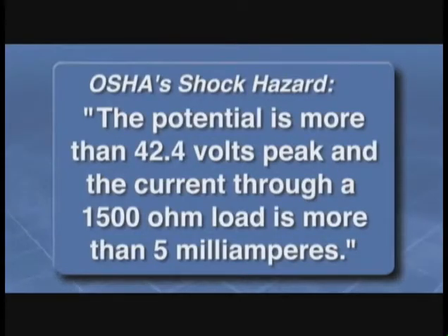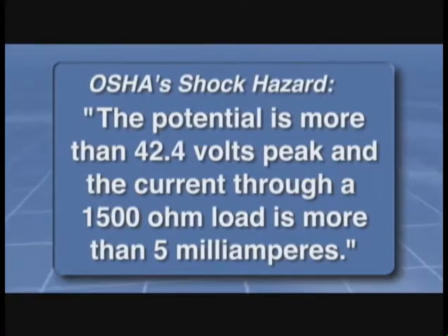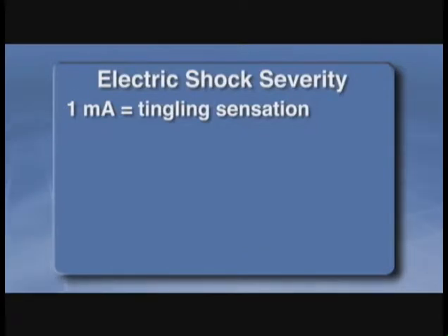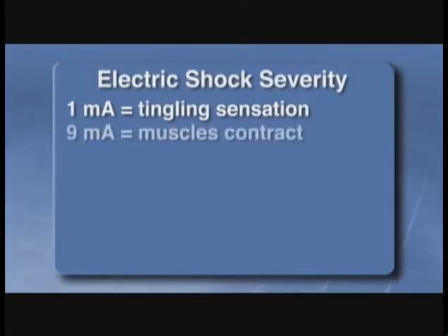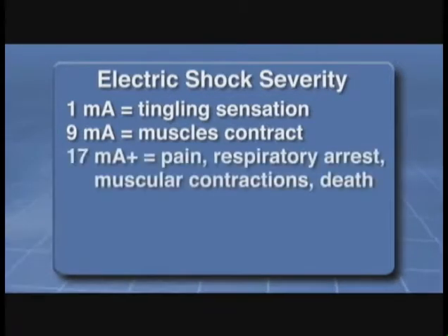OSHA designates a shock hazard if the potential is more than 42.4 volts peak and the current through a 1500 ohm load is more than 5 milliamperes. 1 milliamp of electricity creates a tingling sensation. 9 milliamps will cause muscles to contract, making it difficult to let go.